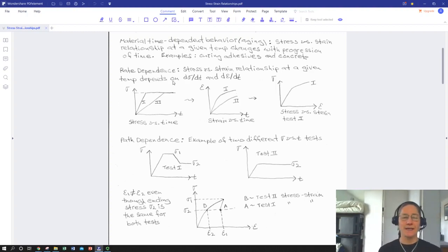Okay, how about rate dependence? A lot of times materials, for those of you in civil engineering, you're going to encounter what's known as dead loading, dead loads where the load is constant, so you can assume that the stresses aren't changing with time. But we all have to work with vibrations. Even if you're building something that doesn't accelerate like a bridge, it will vibrate.